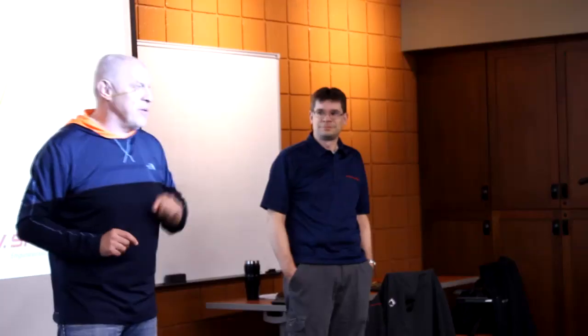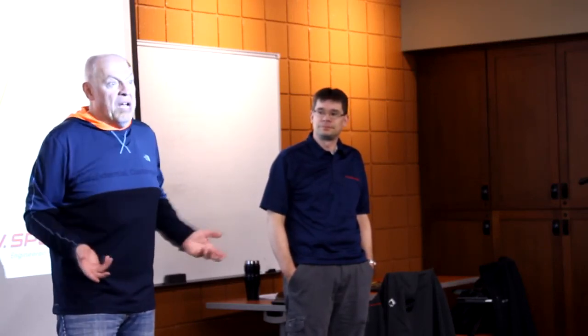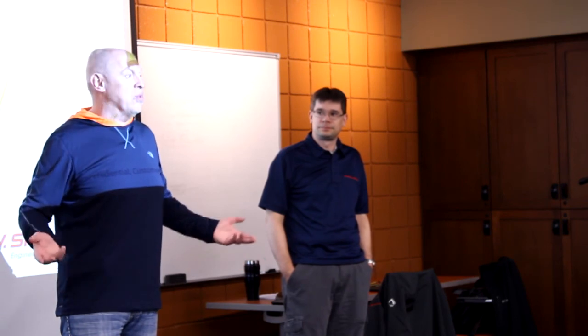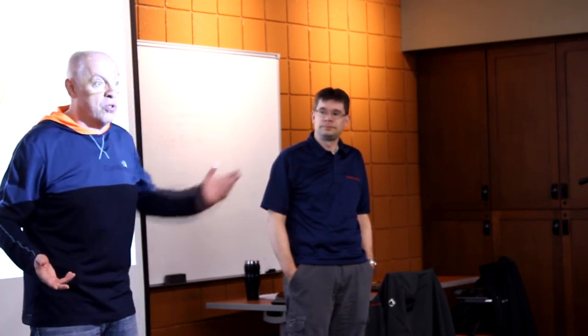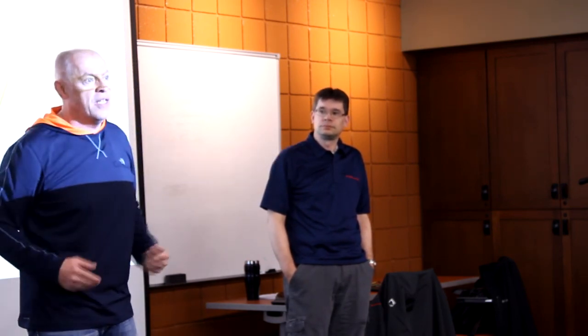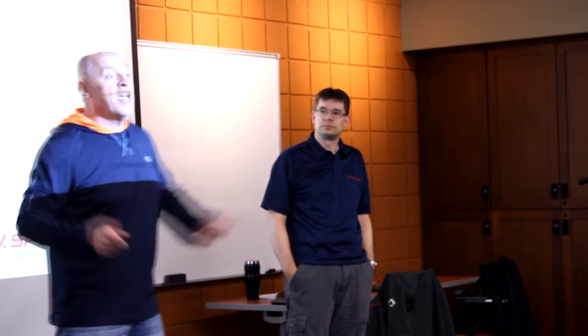Candela, lux. So when you go somewhere and someone tells you, well, I want a lamp to be 100 lux, your immediate question is what? How far away? Thank you, Kyle. Because 100 lux doesn't mean anything to us. What does that mean? Where is that source located and how far away? Then I can calculate the distance and then I know what it is. And you know what it is.